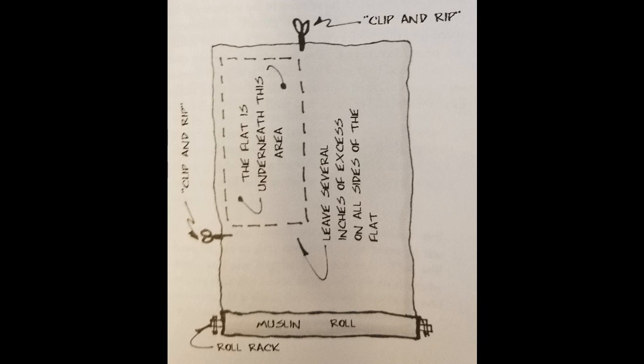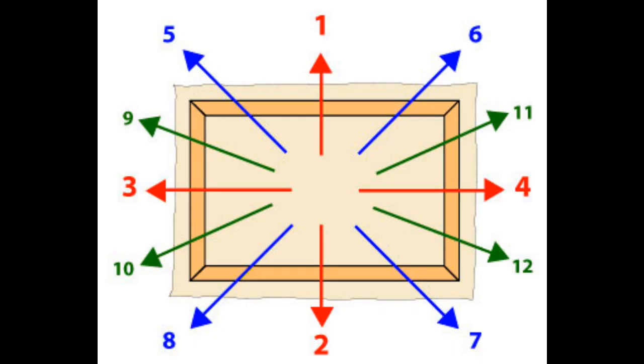Instead of starting in the corners, however, to attach everything, you would typically start in the middle. This is basically to ensure that as you work towards your outer edges, everything is stretched nice and tight so you don't have any wrinkles show up in the fabric once you are finished.